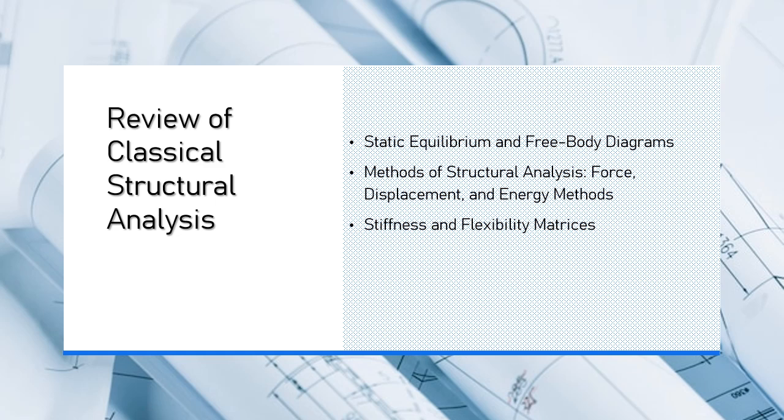Apply the force equilibrium equations ΣFy = 0 to find the vertical reactions at the supports, and ΣM = 0 to calculate the moments at one support and find the unknown reaction force at the other support. For example, if a uniform load was applied along the length of the beam and a point load P is applied at the center, the reactions at the supports can be calculated using these equilibrium equations.